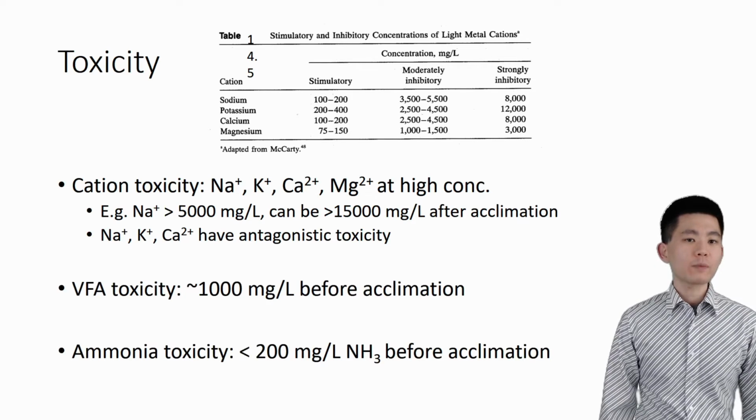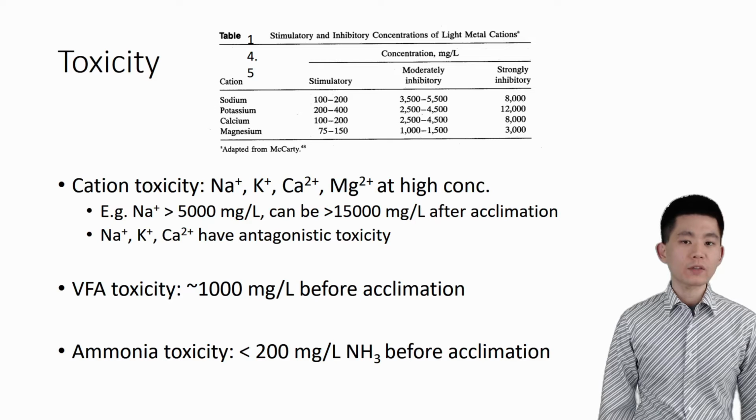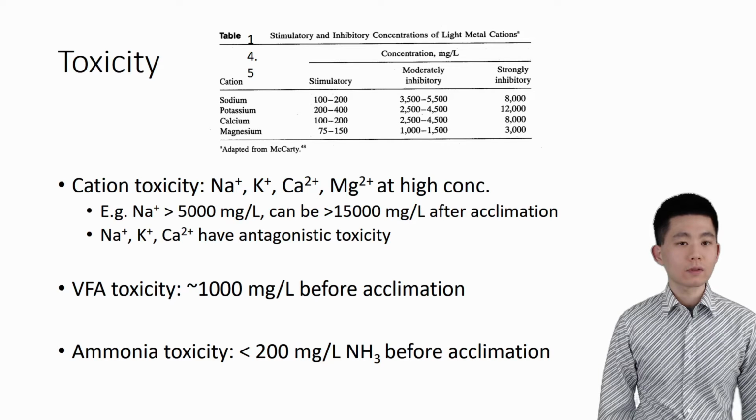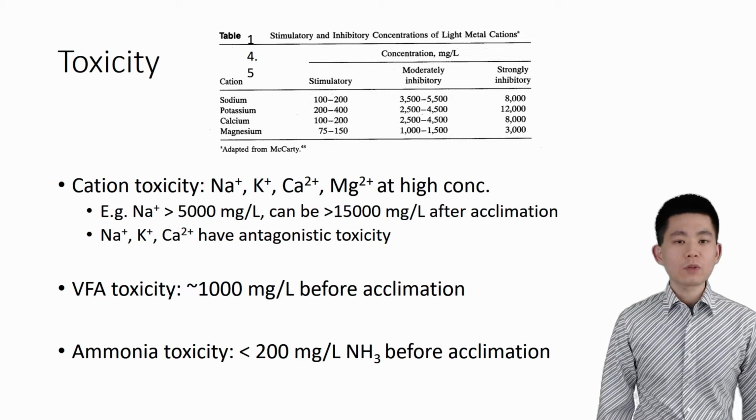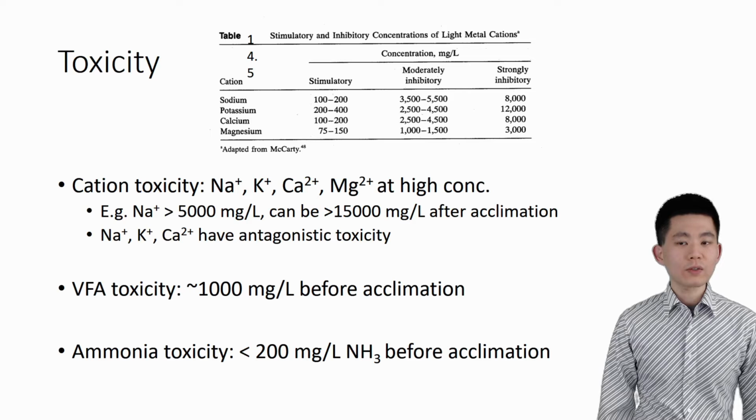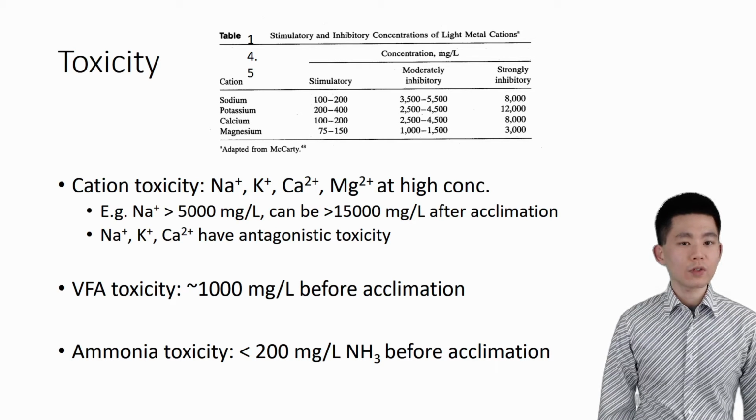As we have covered before, fermentation products like free ammonia and free VFA are also inhibitory to several anaerobic bioreactions. Note that the free ammonia and free VFA concentrations are determined by both total ammonia and total VFA concentration, as well as the pH.